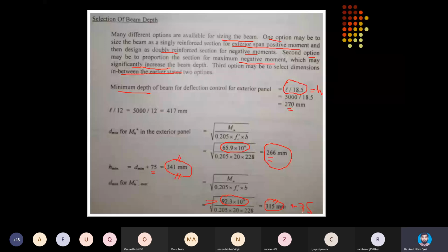However, later on when you will be taught moment redistribution, moment release, and after releasing the moment at some section, redistributing it at some less stretched sections, then this kind of selection of rho max and design will become a point of discussion.